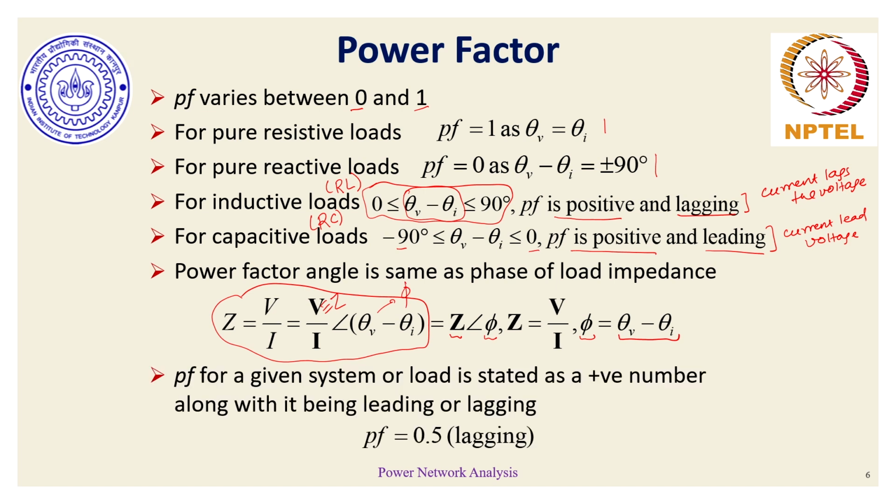So essentially, to summarize, power factor for a given element, network, load, whatever, is always going to be a positive number, and to segregate whether it refers to an inductive element or a capacitive element, the notions of leading or lagging come in. So essentially, when someone asks what is power factor or what is the typical value of power